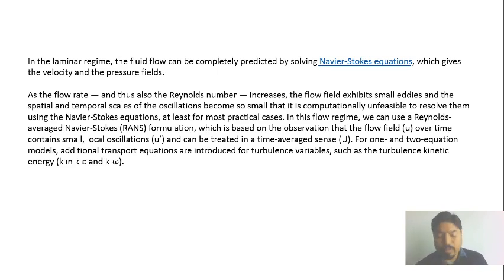In these equations we can add other transport variables which are not properties of the fluid. Again, these are not properties of the fluid, but they are very essential parameters while we calculate any kind of turbulent flow. Here we mention K, which is the turbulent kinetic energy. Why are we talking about it?